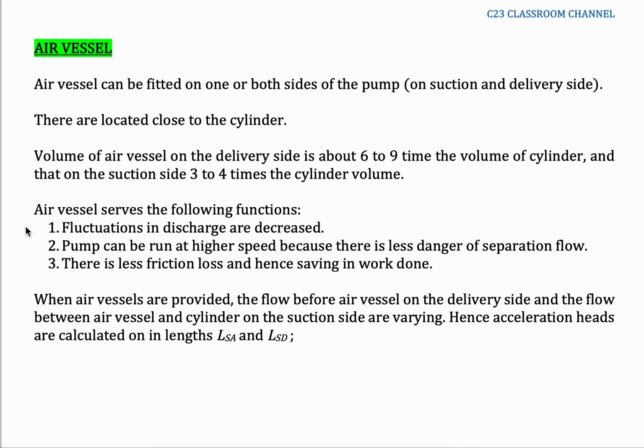Air vessels serve the following functions. First, fluctuation in discharge is decreased. Second, the pump can be run at higher speed because there is less danger of flow separation. And the third one is there is less friction loss and hence saving in work done.